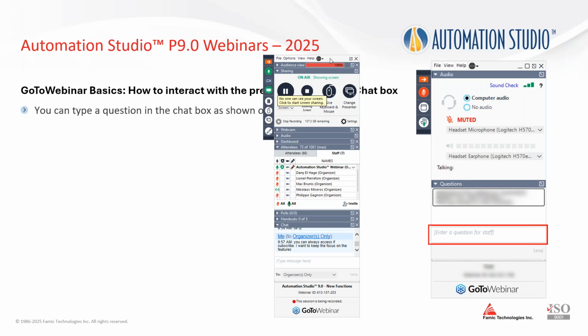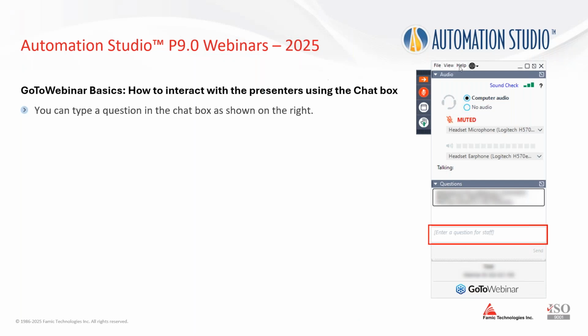So when you're editing your title block, you'll be able to add these sections to your title block, which will automatically fill in these tables. So for the revision, as you create revisions, it will automatically add lines. And the same goes for your part list. As you add components, they will be added.